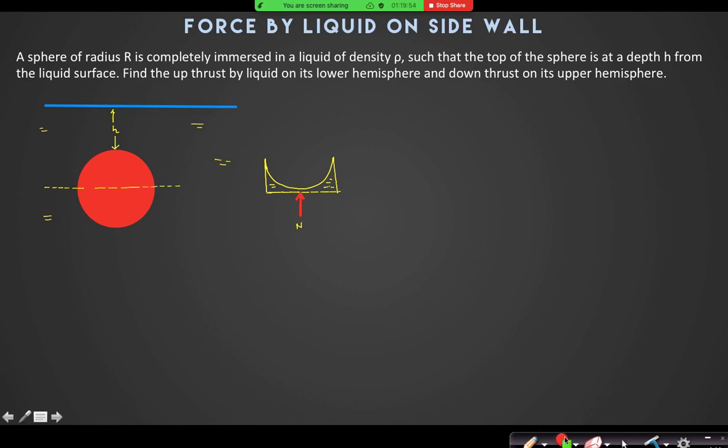So it is the normal reaction. Any other forces there? Weight is acting, right? Its weight is also acting downward on the liquid, right? And the sphere is providing a downward force. Can I say these are the only forces on it? Horizontal forces don't matter. So downward force is this, weight is there and normal is there. Can I draw the free body diagram of this part of the liquid? Yes or no? Yes, sir. So it's very easy to calculate Fv from there.